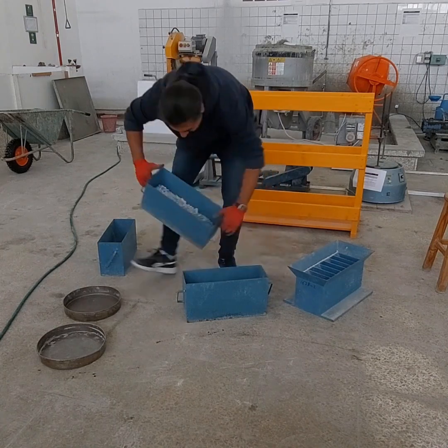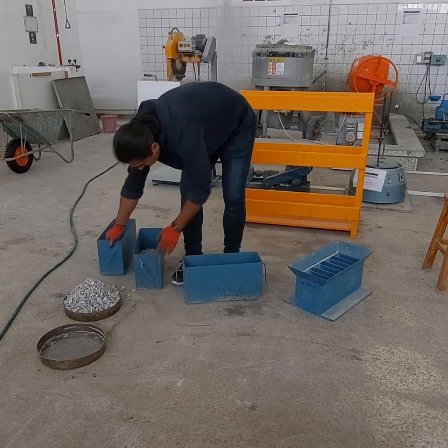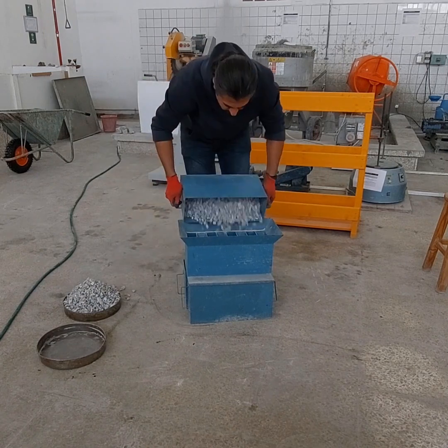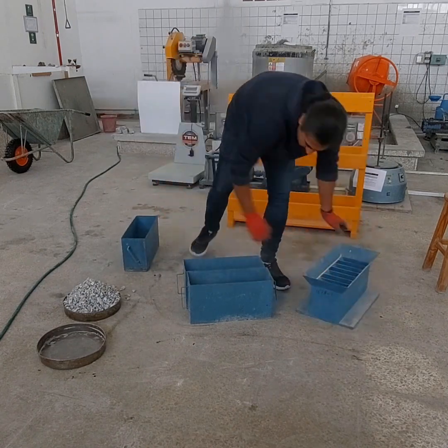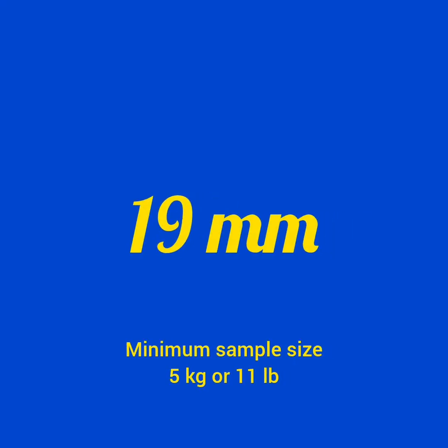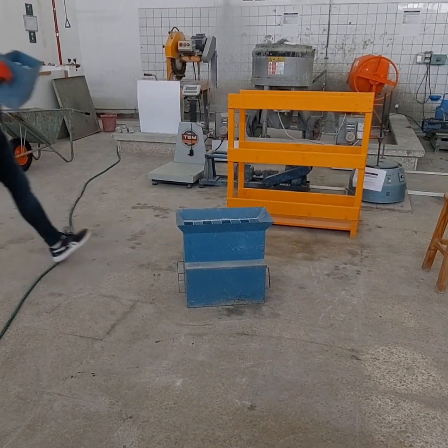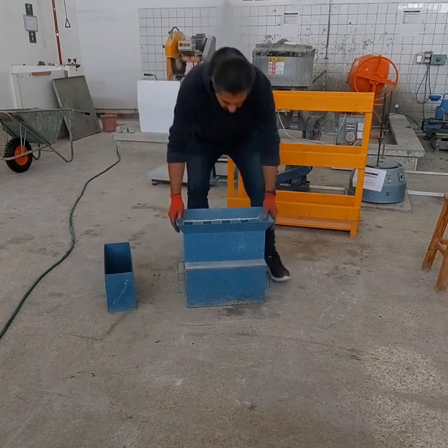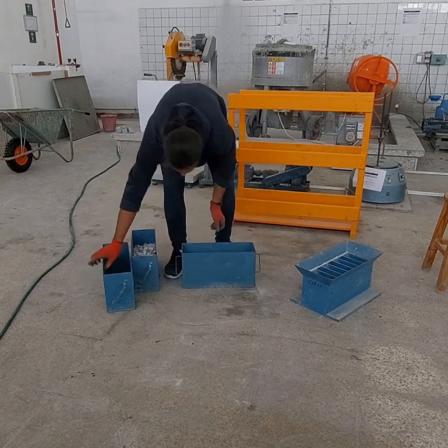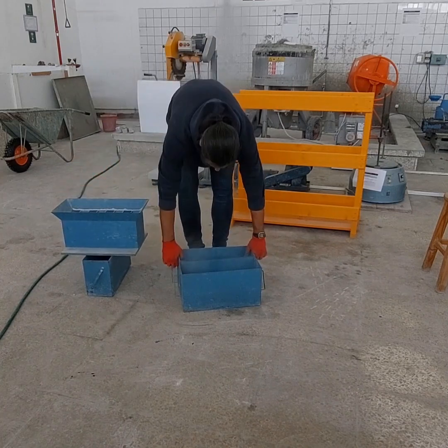To reduce the sample size for testing, I followed the ASTM C702 guidelines. First, I placed the original sample in the hopper and distributed it uniformly from edge to edge to ensure that equal amounts would flow through each chute. Next, I introduced the sample at a rate that allowed it to flow freely through the chutes. To further reduce the sample size, I reintroduced a portion of the sample from one of the receptacles into the splitter as many times as necessary, alternating each side, until the desired sample size was obtained. I repeated this procedure for each size of coarse aggregate.